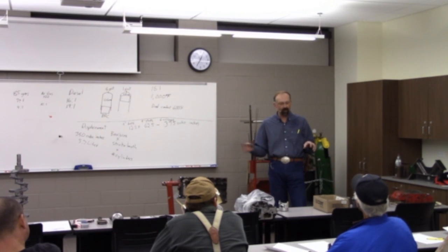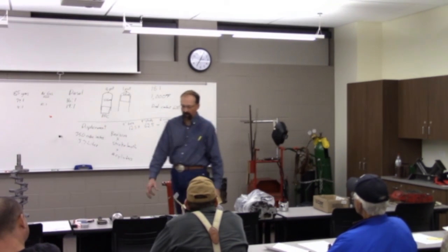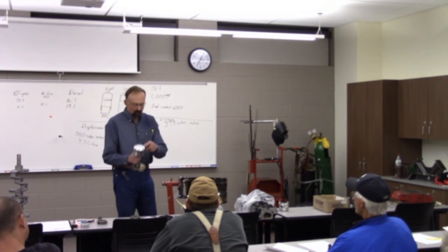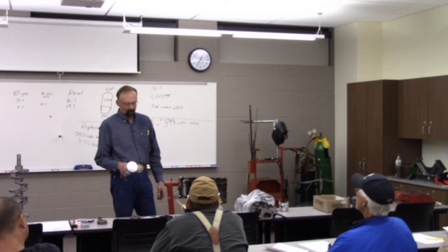In the late 80s, we got fuel injection where there was a computer that took into account barometric pressure and temperatures, and there's half a dozen sensors, and calculated the fuel, and we just didn't have near as much carbon. And that carbon getting down between these rings and piston skirts and the cylinder walls is where we saw a lot of wear.